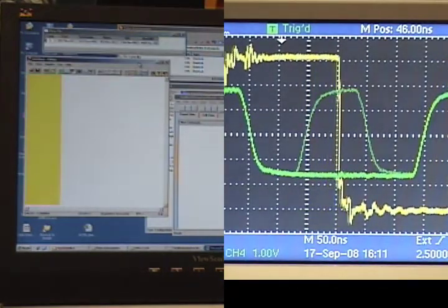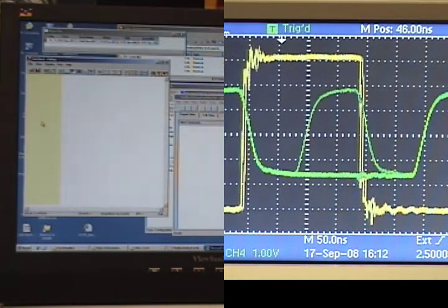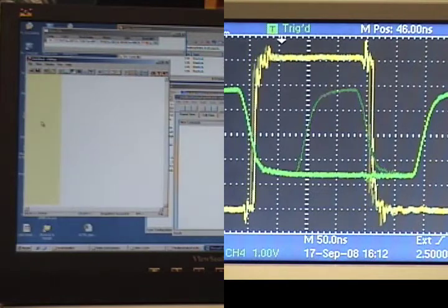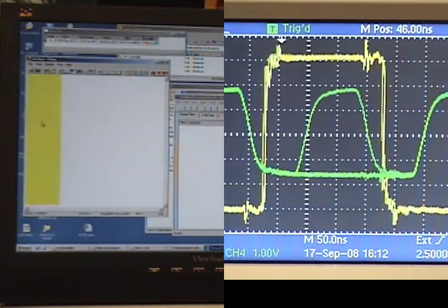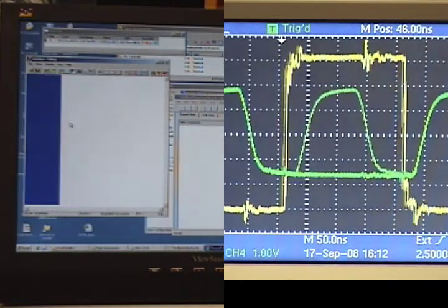Once the 100 loops are completed, the system will report the convert strobe position that results in the best signal-to-noise ratio. It will also export the entire dataset to Excel so we can see a graph of the signal, noise, and signal-to-noise ratio against the convert strobe position.